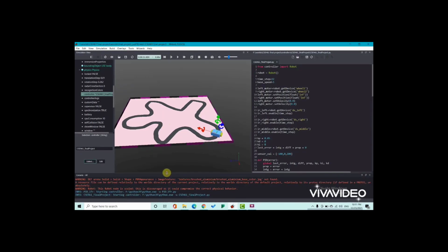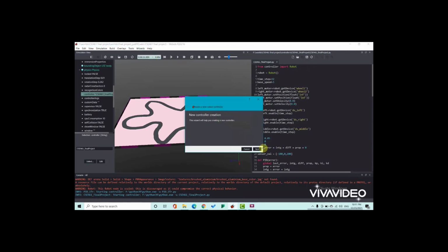Fatiha has already shown how the code works, and I will show the iteration of the code and how the robot moves, compile and run. For that we have to go to the wizard and then new robot controller. After that we can go ahead and create our controller. We will be using the language Python in our case, and next, and create our controller.